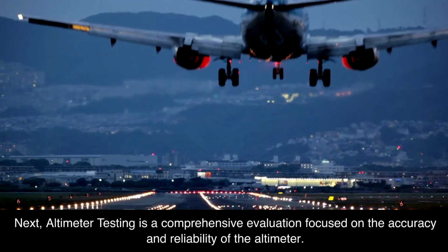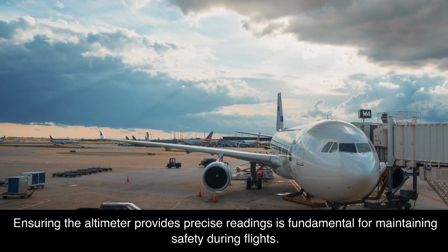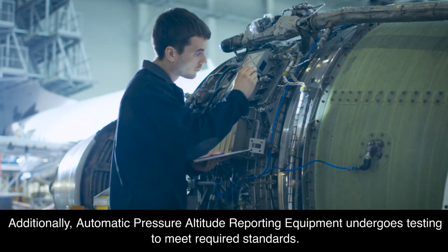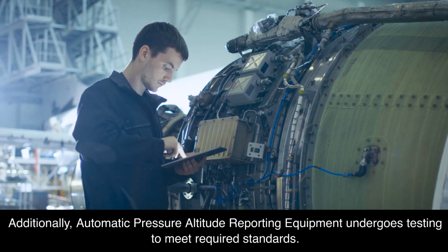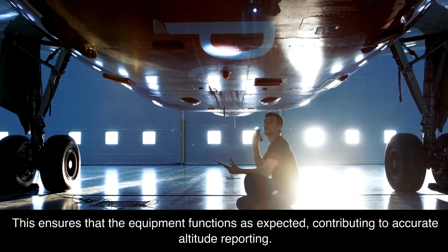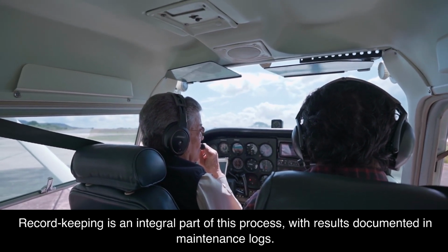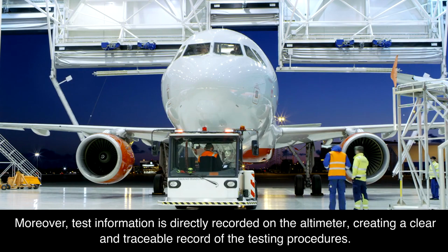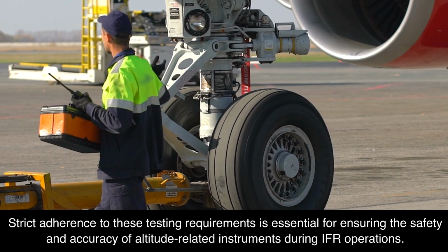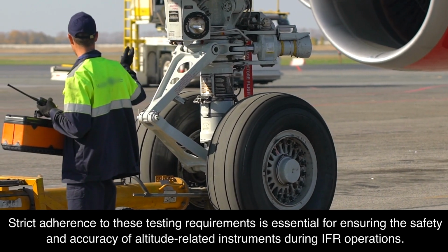Next, altimeter testing is a comprehensive evaluation focused on the accuracy and reliability of the altimeter. Ensuring the altimeter provides precise readings is fundamental for maintaining safety during flights. Additionally, automatic pressure altitude reporting equipment undergoes testing to meet required standards. This ensures that the equipment functions as expected, contributing to accurate altitude reporting. Record keeping is an integral part of this process, with results documented in maintenance logs. Moreover, test information is directly recorded on the altimeter, creating a clear and traceable record of the testing procedures. Strict adherence to these testing requirements is essential for ensuring the safety and accuracy of altitude-related instruments during IFR operations.